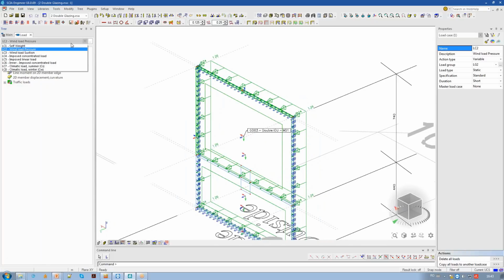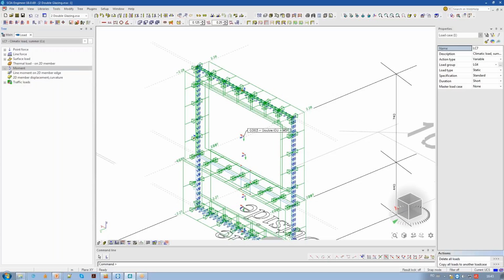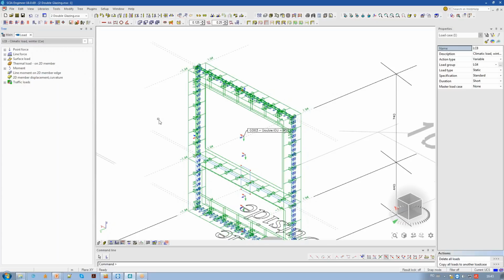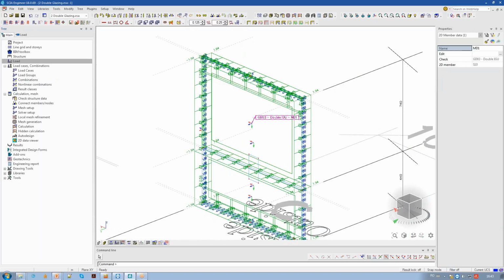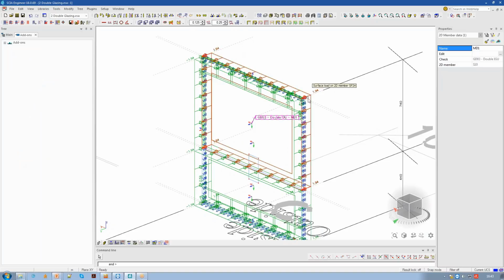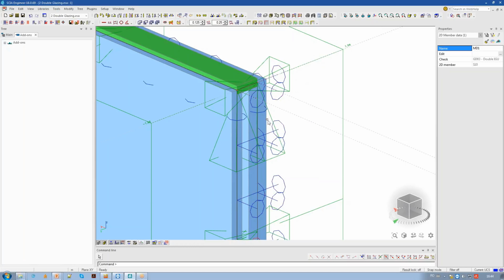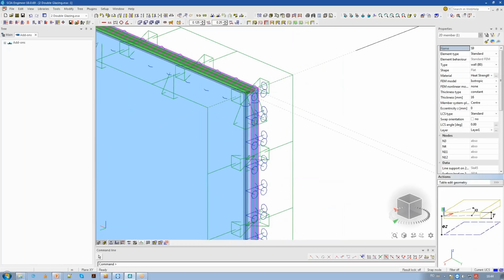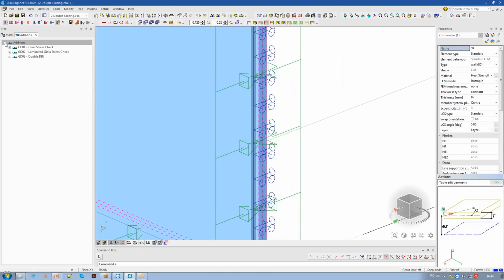So there are different loads here. There are the wind loads and the wind load pressure and suction. Imposed concentrated load in case of impacts or even maintenance loads. So if we have a rail here, and this climatic load during summer and winter has been calculated by the software. So the way we work with insulated glass, we have to model the glass panes at exactly their distances. So actually here we have different thicknesses for the elements. As I said before, they can be built from single layer or laminated glass.